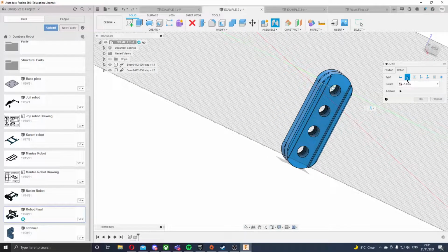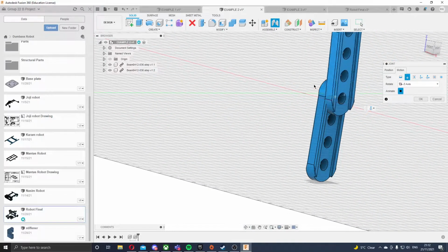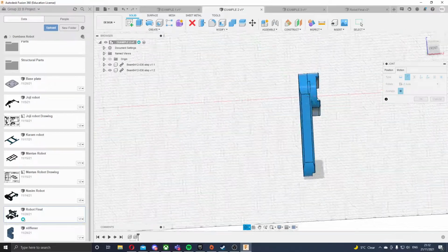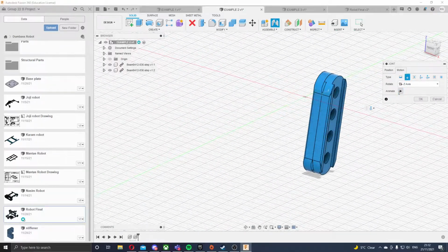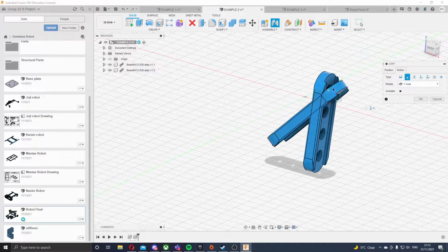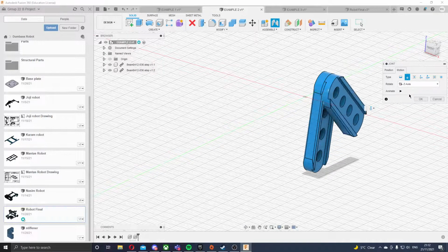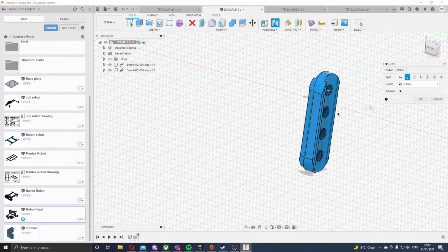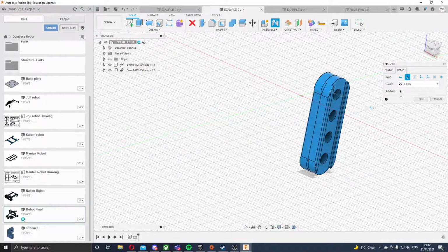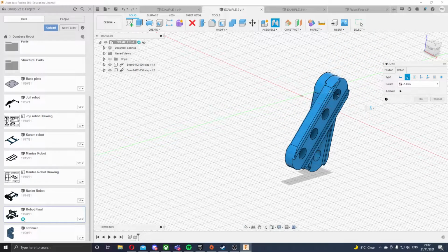If you want to see where your component is moving and you want to see it move more, you click on the animate button, and this will animate your component doing the same rotation again and again, just to check if you need this one. You're also allowed to rotate along different axes. Of course, this would be an impossible rotation, but if your rotation is incorrect, you can always change the axis. In this case, I would probably use the Z axis.